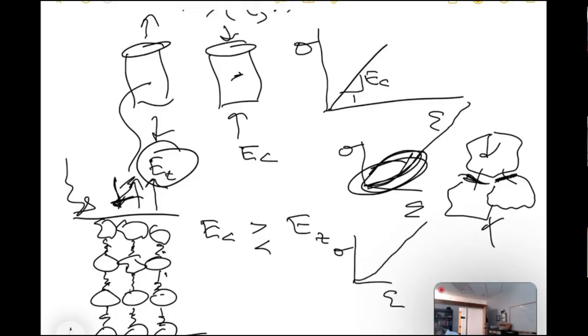This is the granite, it does this. It closes for a while. We don't measure the slope here. We measure the slope in that linear portion. And this is the slope we typically measure. And that's what we call the modulus of the granite from a UCS test.